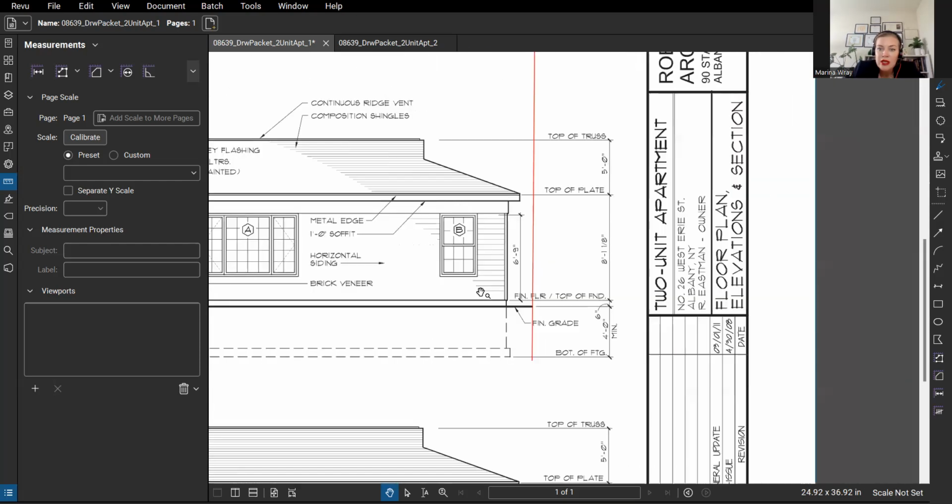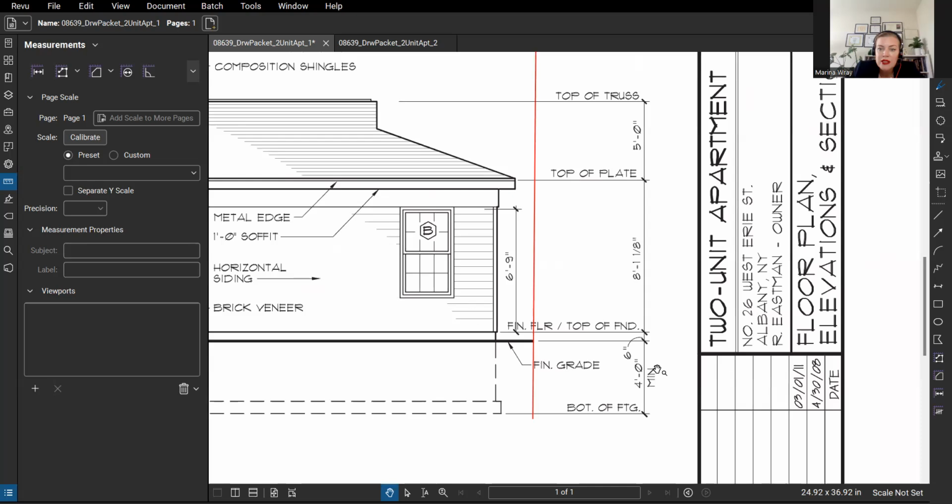So what else you see here on the elevation is the height of the building. And here you can see the dashed line. That's what we learned in the textbook. There are different types of lines, and this one is dashed. That means that it's not showing. That is the underground, the substructure, and this is the superstructure above the ground.